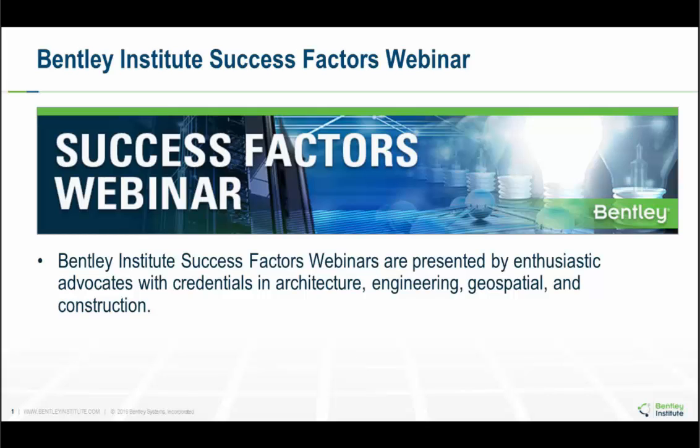But that's my understanding. Another question is, can you ignore P delta effects if your structure has a height less than X amount of feet? I guess this is again related to whether we use the P delta or not. Right. The height of the building is not the issue. It's the stability of the members, and so height of building is not one of the thresholds that I've seen codes address. It's a matter of what the stiffness and the loads and the strength are.